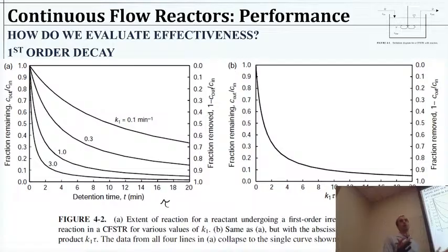We have to treat a certain amount of flow, and now we need to know, can we change our rate constant, or do we have to just change our volume to have a bigger volume to achieve a different residence time? Maybe our reaction is limited to a particular rate constant. We know that, that's just the way it is, and therefore we have to build a bigger reactor because we have to treat the flow, right?